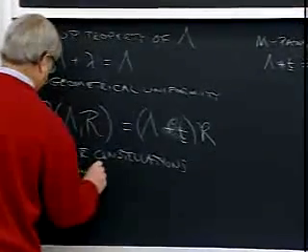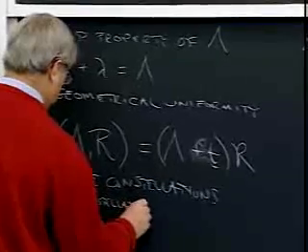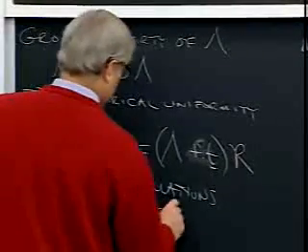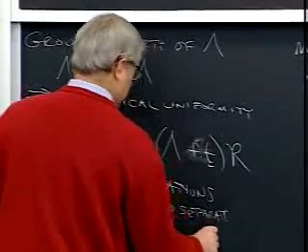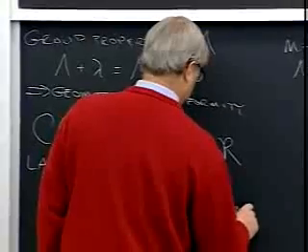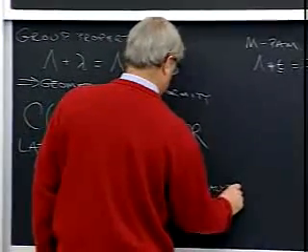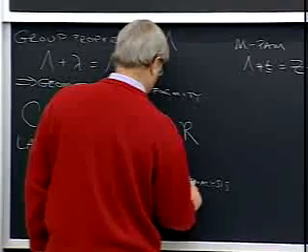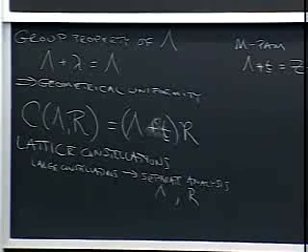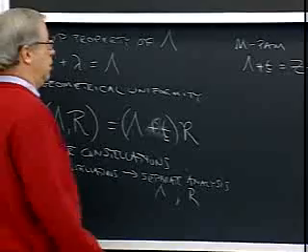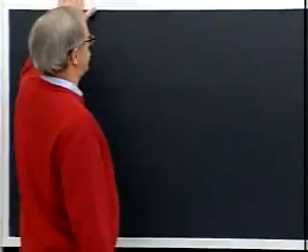And furthermore, for large constellations, meaning as we get well up into the bandwidth-limited regions, large nominal spectral densities, we're going to be able to separate the analysis into lattice properties and region properties. And we'll basically be able to just add these up to get the overall analysis, by making some judicious approximations that become exact in the large constellation limit.